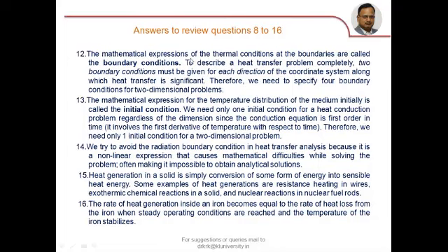And I told you in the beginning also, if you have a second order differential equation like d square T by dx square equal to 0, to solve that equation you need two conditions. And those two conditions are with reference to the x-axis. At x equal to 0 how much, at x equal to L how much, or at the middle how much. So with reference to the position, a point within the body, we have to specify the conditions. So those conditions we often specify